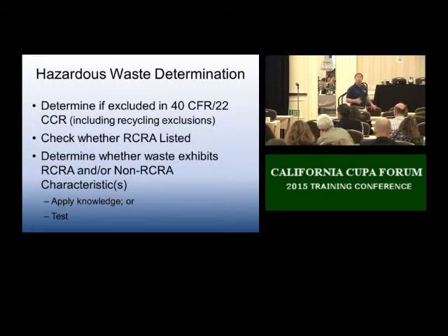Certain wastes appear to be a federal waste. That makes them RCRA. But some wastes that exhibit a RCRA characteristic may be excluded, so you would never give it a RCRA hazardous waste code because it's not a RCRA hazardous waste. There are certain wastes that are hazardous wastes because California does not exclude them, but they're excluded federally. So when I go to classify my wastes, the federal code under RCRA would never apply to that waste stream.